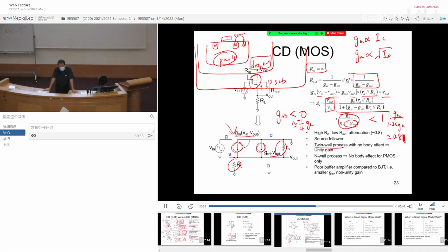Right? So SiGe, HBT, BiCMOS. Why do people like this kind of process? CMOS is good for digital, low power. But bipolar is good for power amplifiers. So together they can build an RF chip, everything self-contained. Okay?